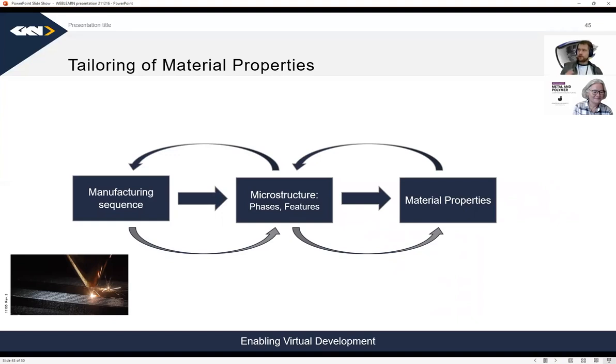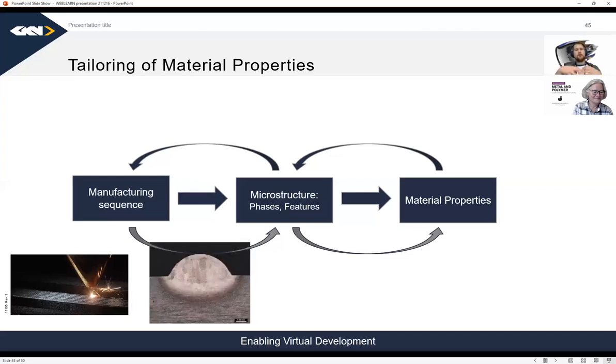The buy-to-fly ratio is this: if we buy a forging and then need to machine away a lot of the material to get the final product, we want to minimize the machined-away part. So for additive especially, but generally also, we need to develop process parameters of the correct quality, so that we get a good amount of penetration in the beads when we build them, and then when we build the next one next to them as well.